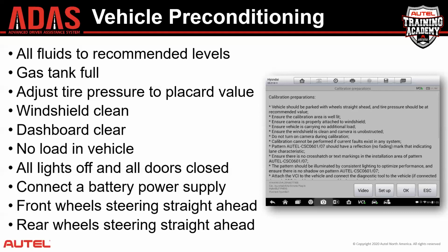Ensuring all the doors are closed. An open door during a calibration would cause some leverage as the weight of the door slightly tilts the vehicle to one side or the other, and that can throw calibration off. It's a very good idea, I strongly urge you, to connect a vehicle battery power supply to maintain battery voltage during a calibration.